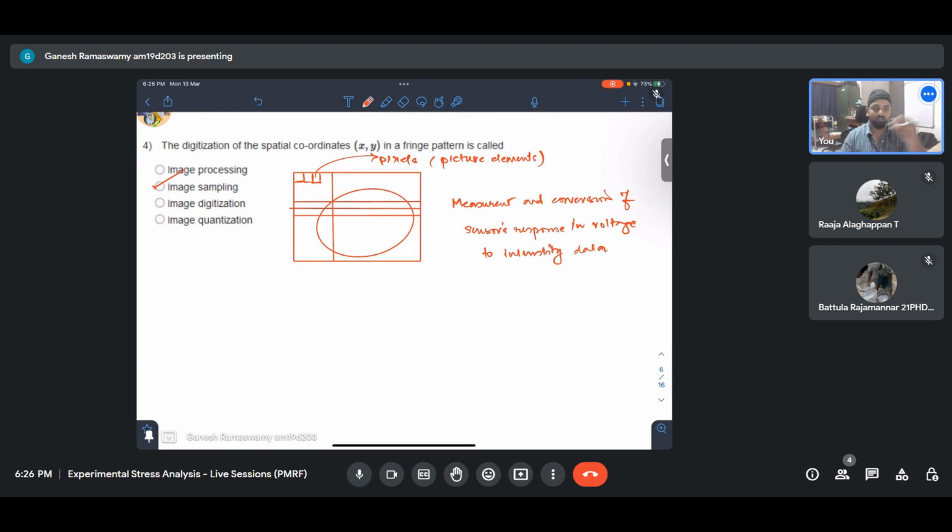Essentially, there will be some errors and noise. All these things will creep in, and it also depends on what technology we are using. For example, CCD technology, charge coupled device, as spoken about in the lectures also. Those have an array of pixels where, once you take a photograph, the charge accumulated because of the optical response by the wafer is made to move down and read sequentially. So that is one technology.